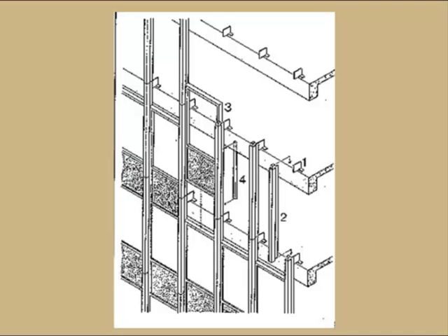Definitely, and I think the definition clears it up, but maybe when I was younger, before I got into building envelope technology, you see these amazing structures. Picture the Sears or the Willis Tower in Chicago, and I was thinking to myself, how in the world can this building that's 1,000 feet tall be structurally sufficient just on windows? But having known how curtain wall technology works, it's really just a framing system that transfers the gravity and the wind loads of that curtain wall to the building frame.